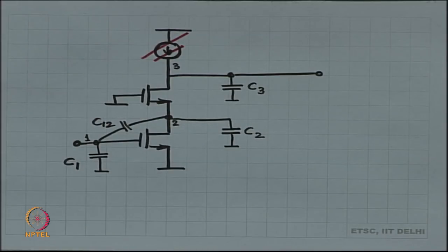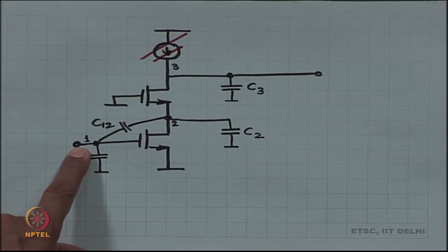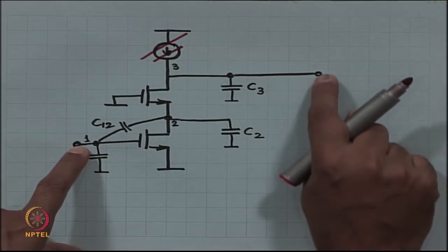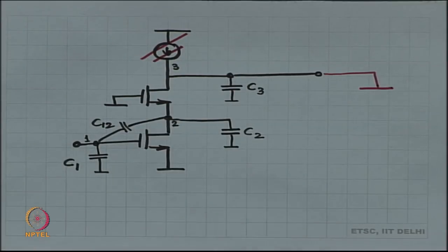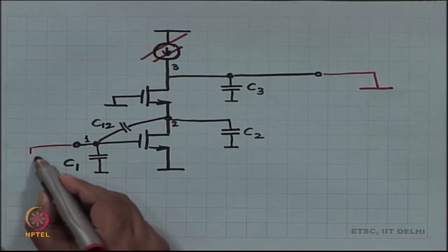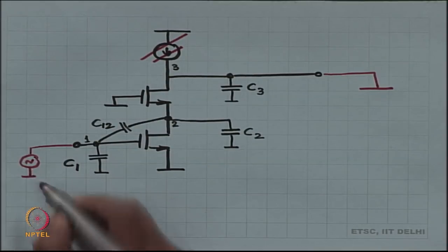Okay. So, what do you want to do first, short circuit current or output impedance? It does not really matter. Let us do the short circuit current. For the short circuit current, we are going to apply a voltage at the input and short this output, and measure the current. This is the plan.